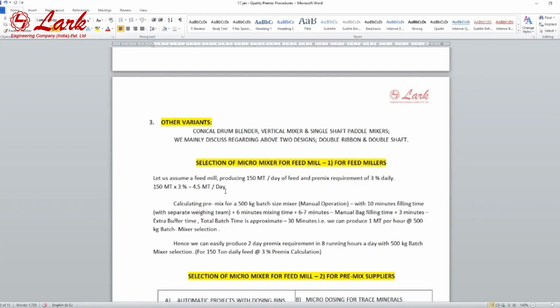So in that case, instead of putting in a separate or smaller hammer mill, and instead of investing more in machines, we reduce the RPM of the hammer mill from 2800 to 1800 or 1700. You can do it even to 1837 also. Yes, to that micro level you can go.